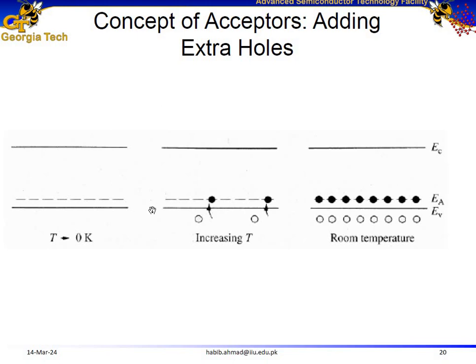of the semiconductor. So at room temperature, electrons jump or transition from the valence energy level into the acceptor energy level, leaving behind holes. And in semiconductors, for the flow of current, we either need free electrons in the conduction energy level, or holes available in the valence energy level, or the combination of both.